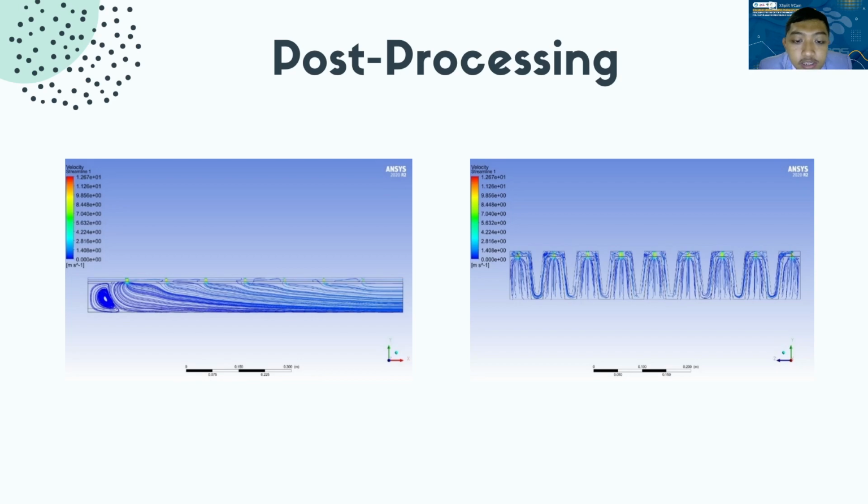And the second figure is the streamline contour on the side of the ZY plane, where the airflow in the space between the absorber plate and the jet plate is also affected by the airflow that moves from below, originating from the wave side of the other plate, in addition to the influence of the airflow through the jet impingement. The flow is in the space between the bottom side of the absorber plate and the bottom plate, where there is no jet plate inside.